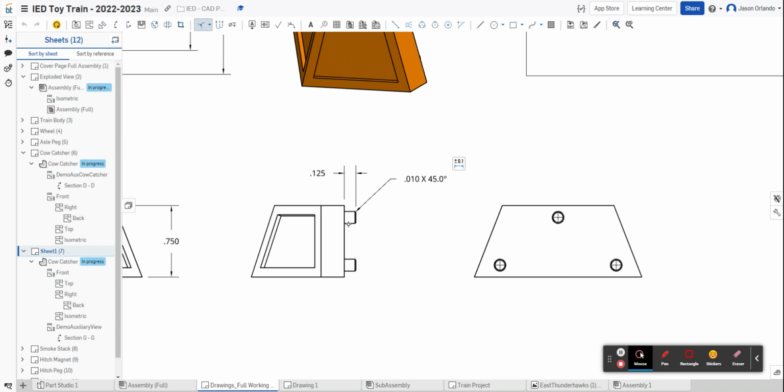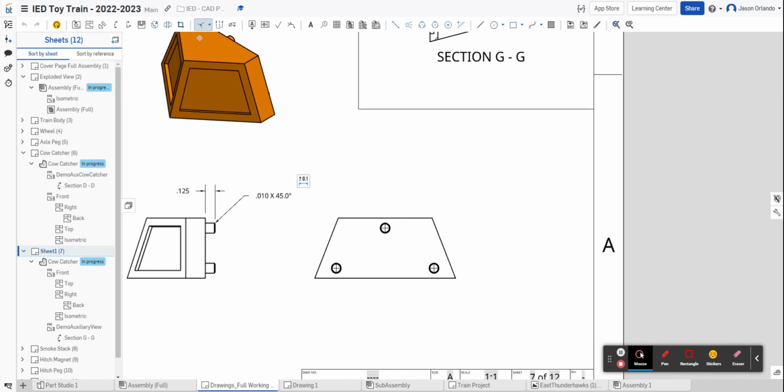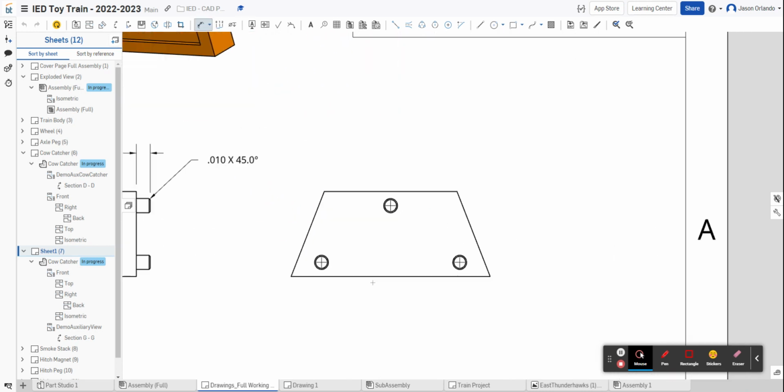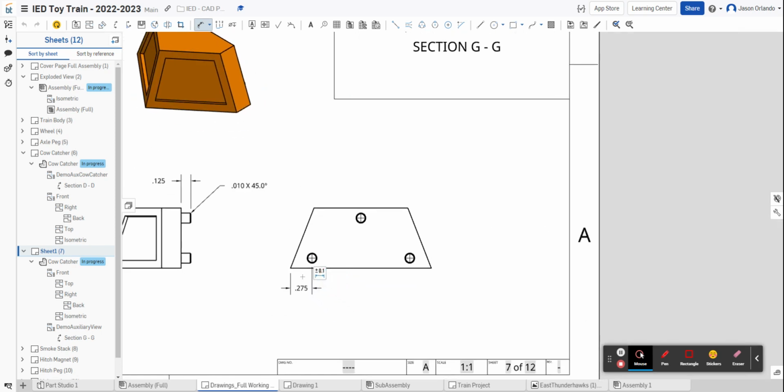All right, so now we understand how long the tab is. We understand that it's got a chamfered edge and the details of that chamfer. On the back side, we are going to locate the tabs. I'm dimensioning from this corner to the center marks.